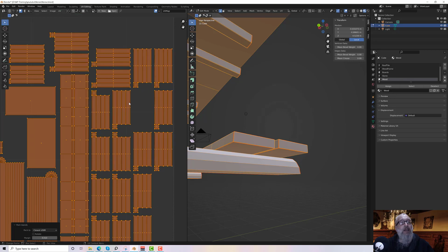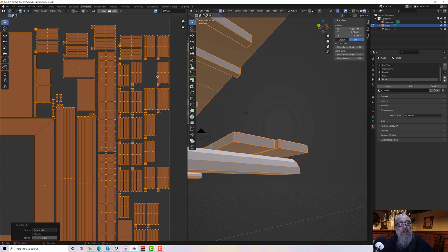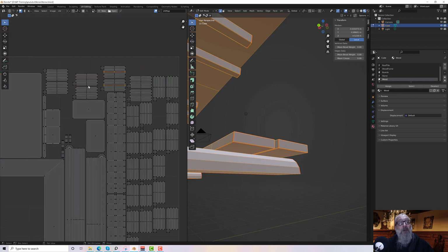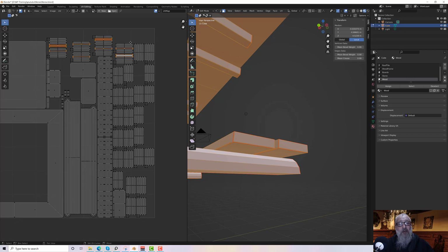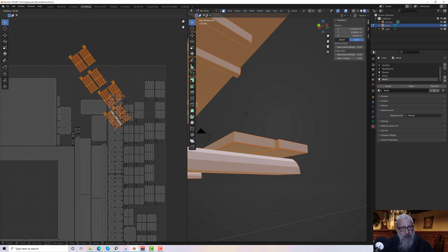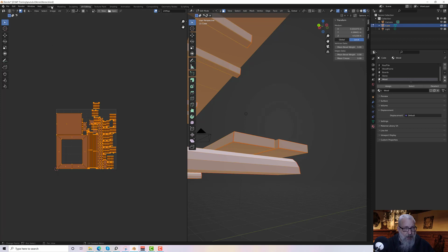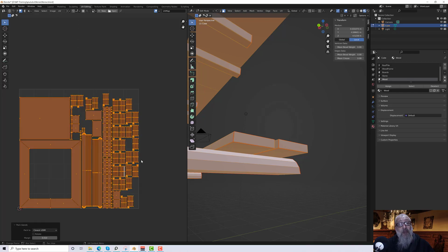It's worth noting here that some of these things are the wrong way around. Let's try a pack, and yeah, some of them are still the wrong way around, so we've got to grab these ones that are pointing in the wrong direction. There. And rotate them around manually. So Control L, R to rotate, Control to constrain, and then A, pack, but make sure rotate's turned off.